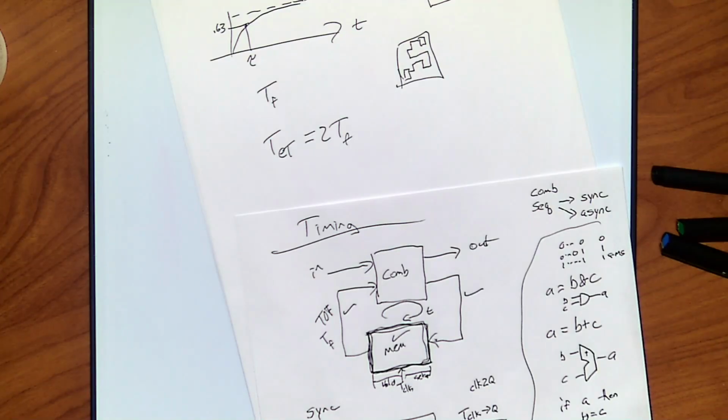If I go to the really super fast ones, carry look-ahead adders, that can do things in 2 to 3 logic gates total, no matter how many bits. The number of input wires per gate becomes linear to the number of bits. You now need AND gates with 128 wires coming into them. Right? This becomes impractical.